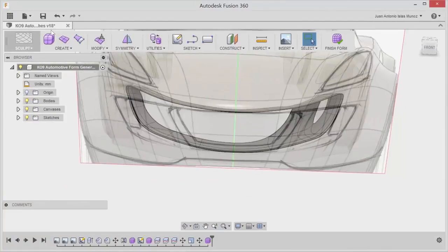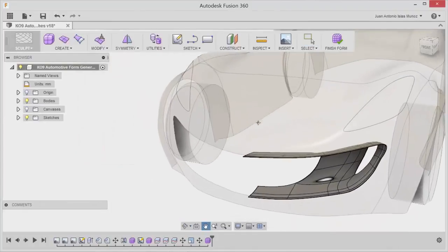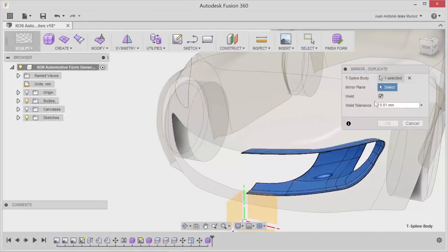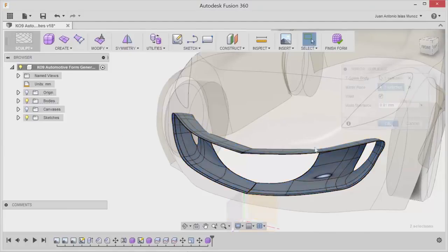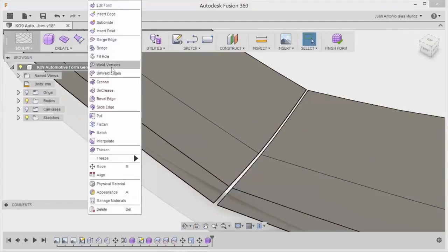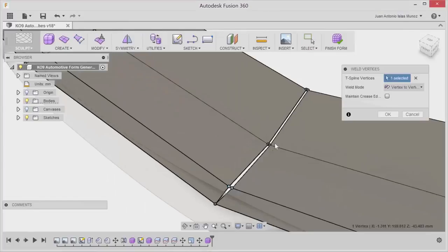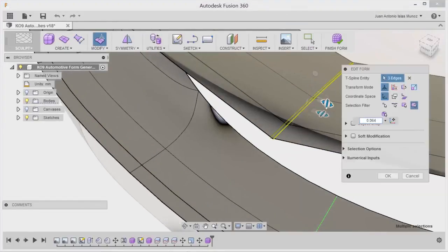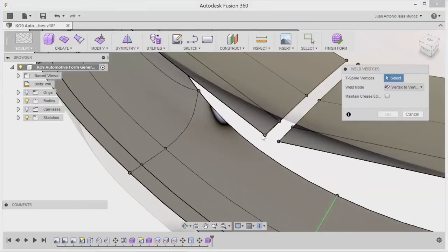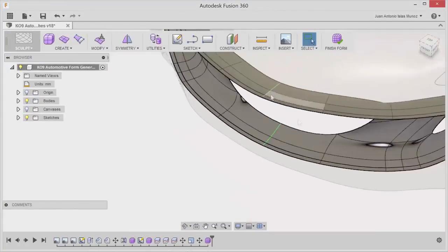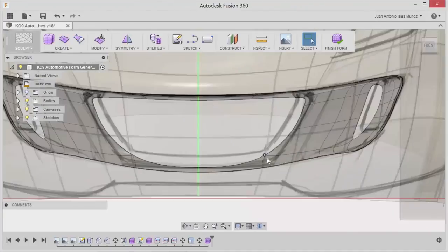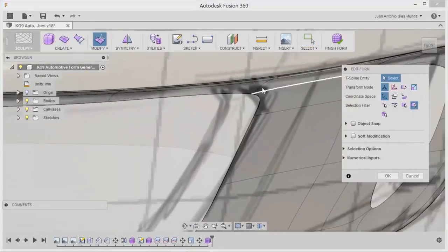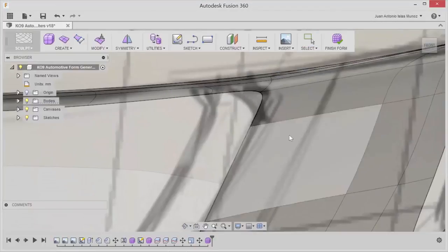Make sure you're working with symmetry. If necessary, delete half of the body and use Symmetry Mirror Duplicate. You can use weld vertices to join. In this case, we see two overlapping edges. You can separate them using Edit Form before welding. Adjust the topology to match your canvas and add edges wherever necessary to gain more definition or harsher surface changes.